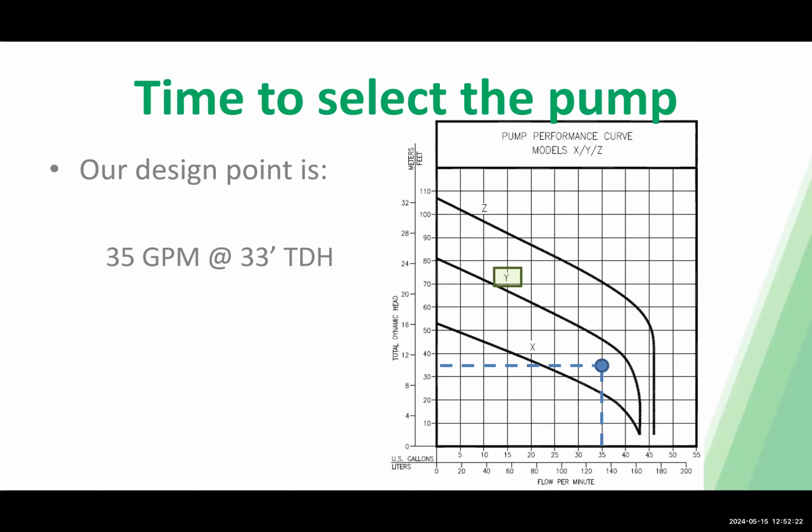I think for the life expectancy for this specific application, you'll notice that you're likely going to be operating far to the right of that pump curve. So the life expectancy is likely not going to really change. Again, you need to be more towards the middle to be the most ideal. But in most cases, if the pump curves are similar, your life expectancy is not going to change.